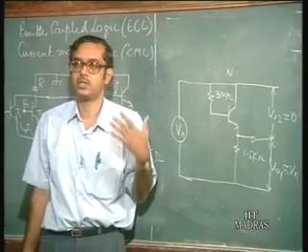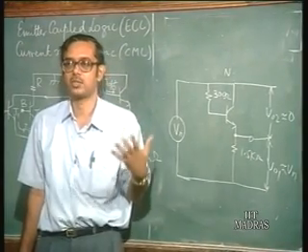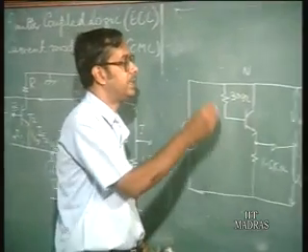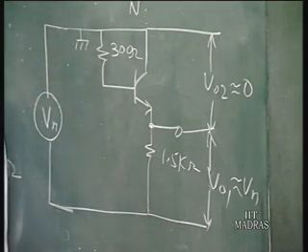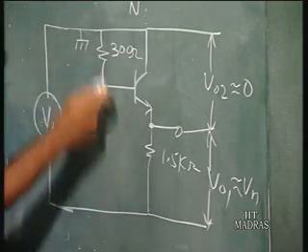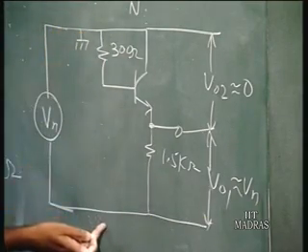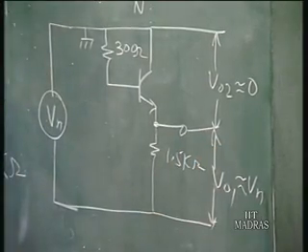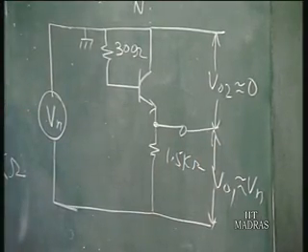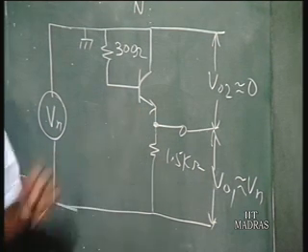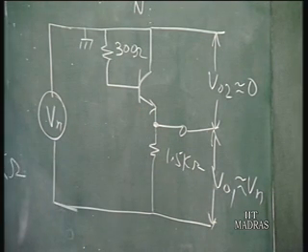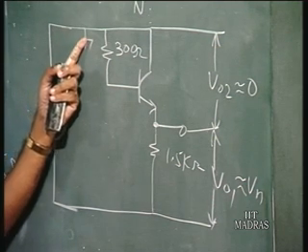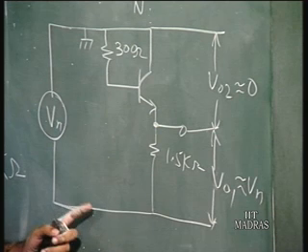And you see, in any circuit the ground is always the reference point with respect to which you take the output. So, what is advantageous is to make this ground and put a negative power supply, rather than putting this as VCC and this ground, in which case you are taking the output across these 2 points. So, that is one reason why it is advantageous to have the upper point voltage here as ground and this as minus VEE.